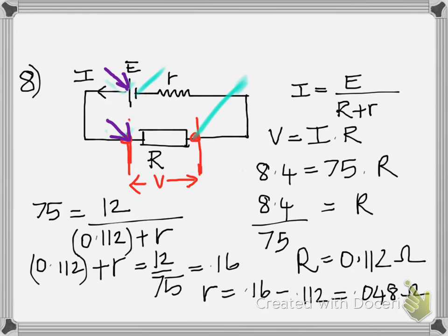Okay. Now you also notice that the internal resistance is deliberately kept small. It has to be small. Otherwise the voltage drop will be huge and that will be a useless battery.